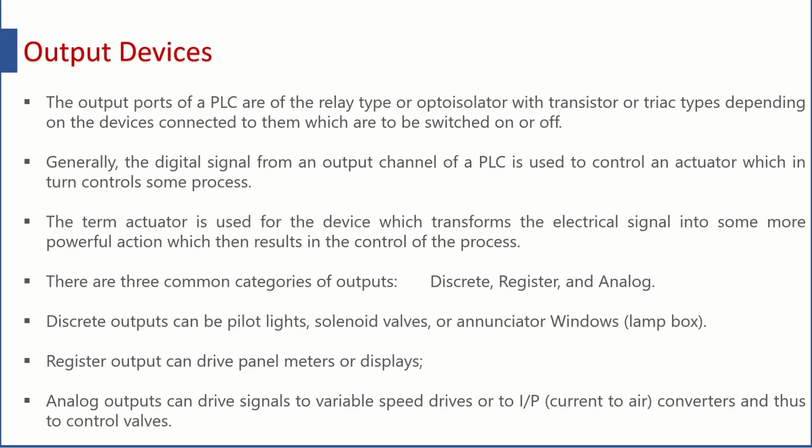Remember that whenever outputs are concerned, these relay blocks are very important, because if you don't want to damage your PLC, you just allow a relay to work. Now it may so happen that your output device needs very fast switching, then a relay may not serve the purpose. Under such circumstances, you need some faster devices. You may have to use an SCR at the output, you may have to use a solid state relay at the output if you are working at some hazardous condition, like that. Varieties are here also, just like in input devices.